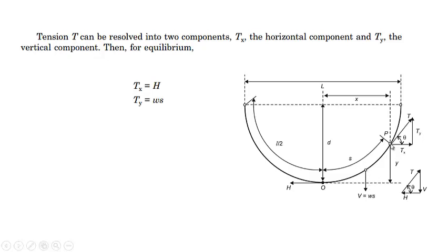And when we find something in kg over here, we are assuming that to be equal to force. Now this is one vertical force, and this is the horizontal force. In equilibrium, the two horizontal forces which are opposite will be the same. That is, Tx will be equal to H, and Ty will be equal to the vertical force, Ws. So this is at the equilibrium point.